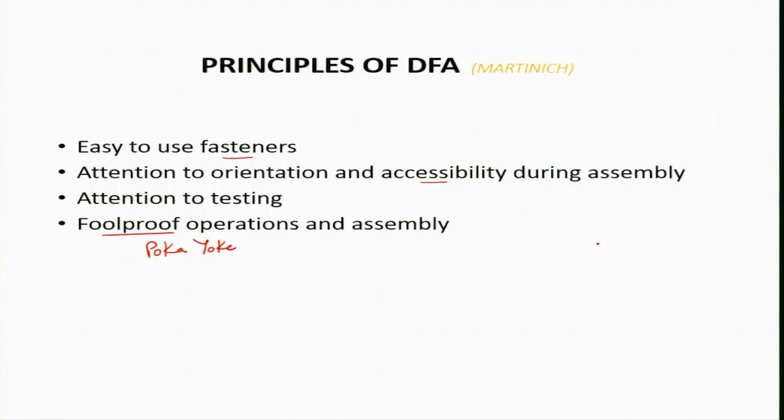Just like the SIM we use in the mobile, it has been designed in such a manner that it gives a poka-yoke. You cannot insert the SIM into the mobile in any manner other than the right manner. So that is the kind of design foolproofing of the product, that you cannot insert the component in a wrong manner. It will not allow you, it will not permit you. So that is the concept of poka-yoke. In manufacturing, in processes, the concept of poka-yoke is used at several places.